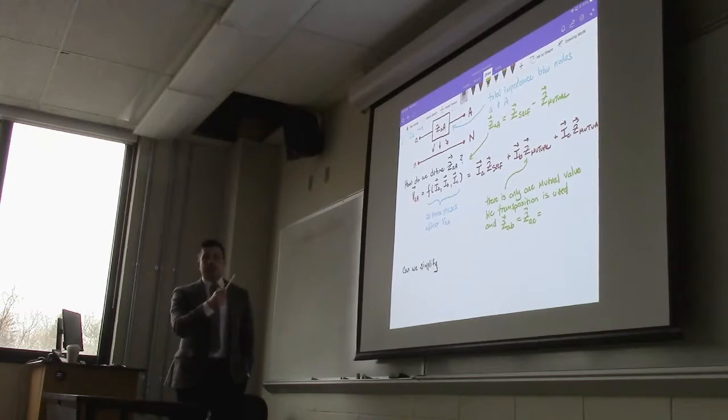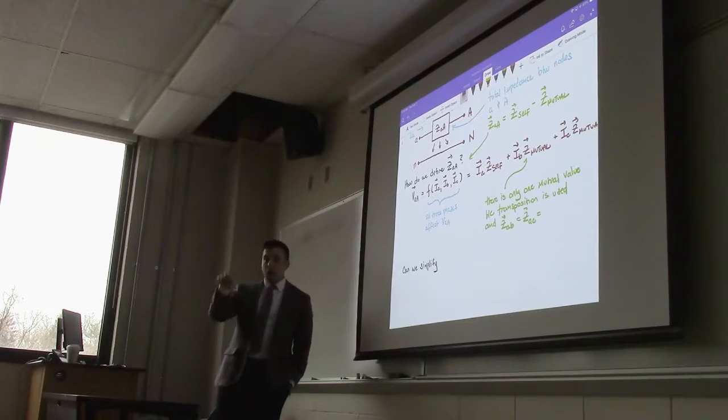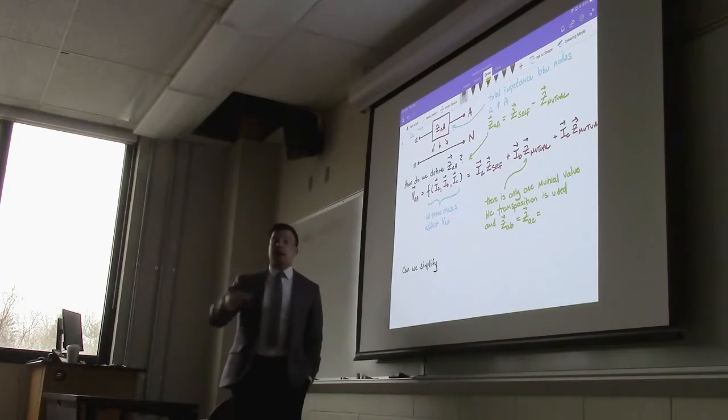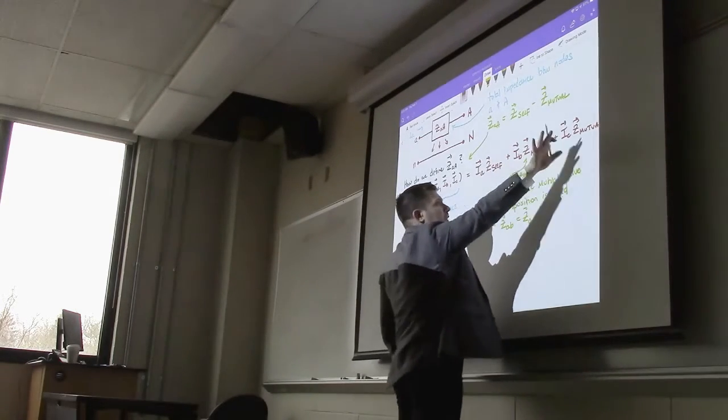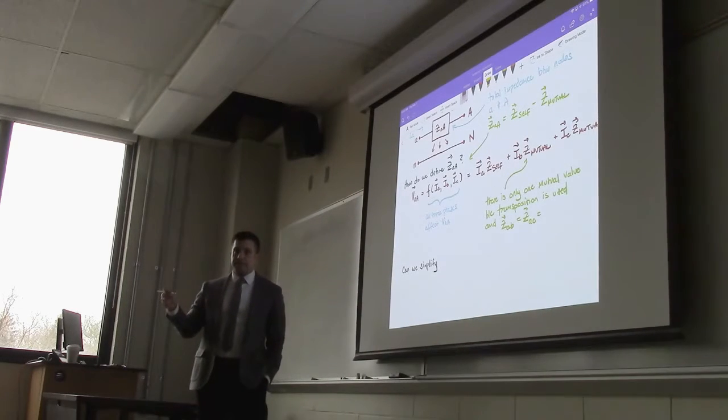The self-impedance is the actual resistance and inductance on that line. That would be there even if there weren't two other phases. So let's say you run a single line by itself, these two go away, you're obviously going to have an impedance along that line.